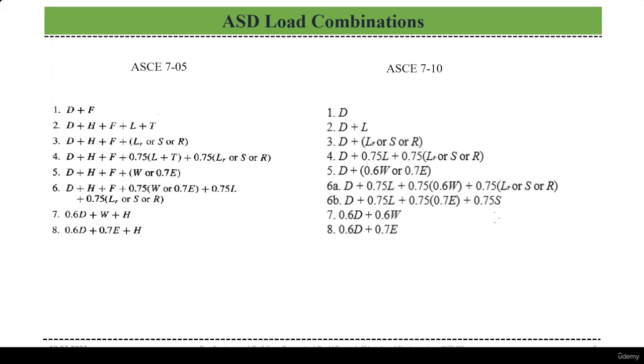If you want, I can tell you the factor. Ultimate wind speed will be obtained by using basic wind speed multiplied by root over 1.6. So based on this, ultimate wind speed will always be higher than basic wind speed.